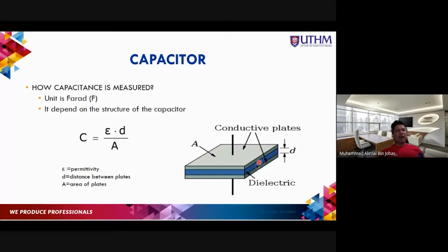So we have air. Air can be a gap also, acceptable as a dielectric. So, the permittivity of these dielectric materials. When I was working with Panasonic, they had one very specific capacitor. They call it a Take capacitor. You can write it down here. Take refers to the Japanese word for bamboo. So they put bamboo as the dielectric material.